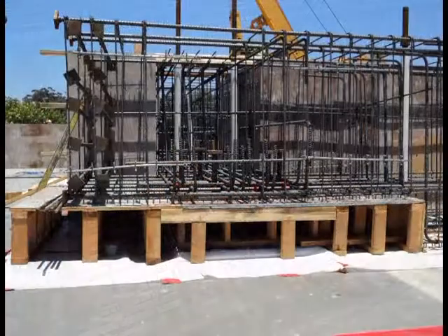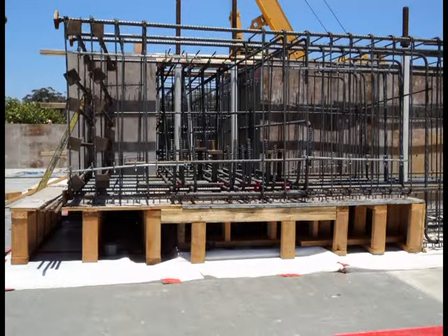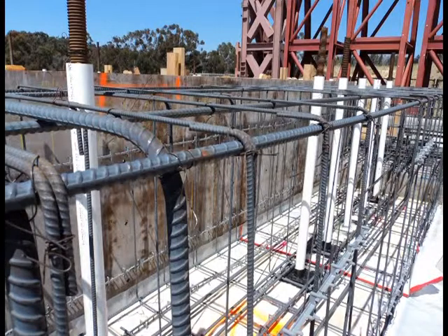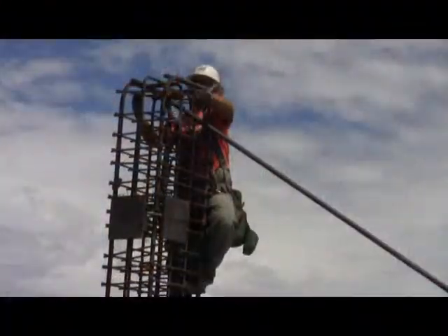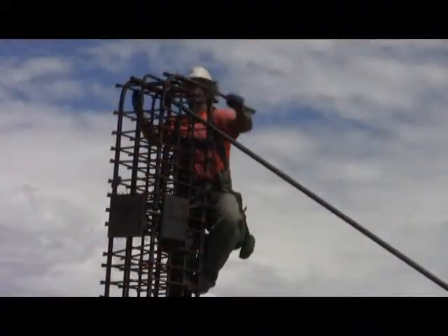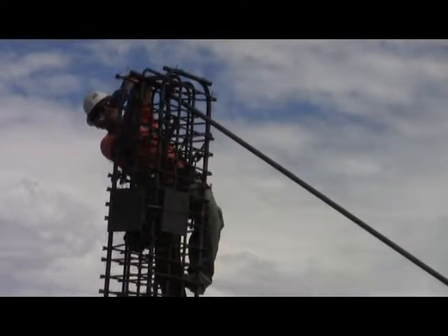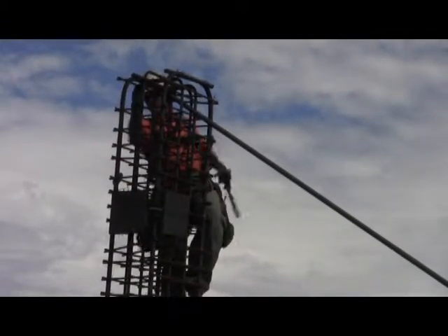The cross-section of reinforcing cages can take any shape based on the complexity and aesthetic factors for the member being constructed, from circular to any other shaped polygon such as squares or rectangles. In this project, the columns were rectangular, and therefore the longitudinal bars were placed in a rectangular cross-section with transverse ties being provided up the height of the column at a constant spacing.